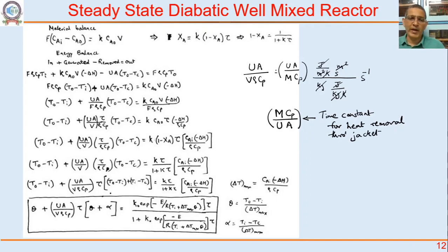So I have one more parameter now. I have rate of heat generation, and I have a rate of heat removal as well. And you see in our expression, from what we had seen in the previous class, A by V appears, surface area per unit volume. Higher the surface area per unit volume, faster would be the heat removal rate, and the time constant will be lower.